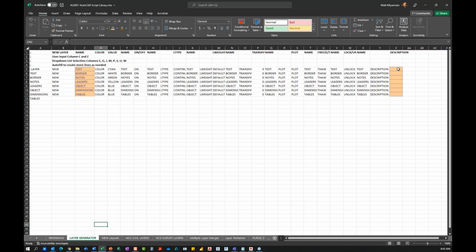The nice one about this is if you want to leave the description blank, you can leave it blank. In some cases, because that's a space, it would possibly cause an issue, but with this one, because AutoCAD is looking for you to type something in, it actually changes the space to an actual space, as though you were typing instead of an enter. So for the description column here, it does actually work if you just want to leave it blank.